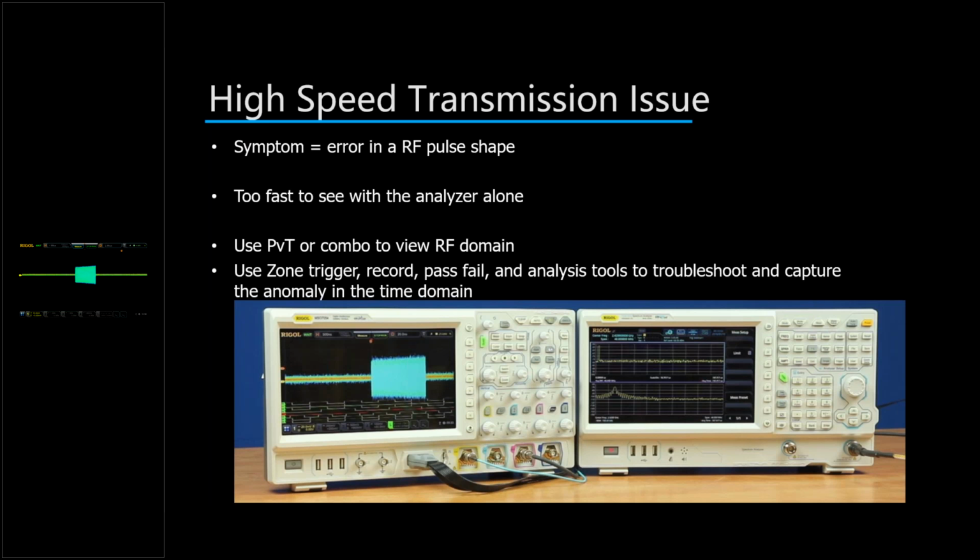Let's zoom out and go out to about a millisecond per division here. Now we can see those pulses, look at them clearly, and zoom in on them. We're able to do that because our memory depth is such that we can capture all those important characteristics out at 2 milliseconds per division and look at that sequence while still getting all the pulse detail, right? So we're able to Nyquist sample these 500 megahertz signals out in time.